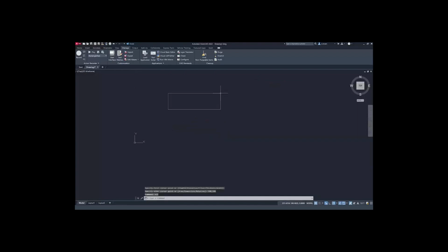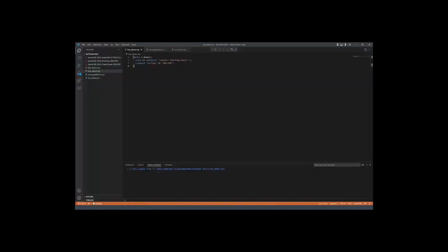But now notice that rectangle has gone over here because the second part of my code here is still telling it to go to those relative coordinates. Or not relative, sorry, absolute coordinates. So there's a few different ways we can get around that. We could either input relative coordinates or we could input dimensions.